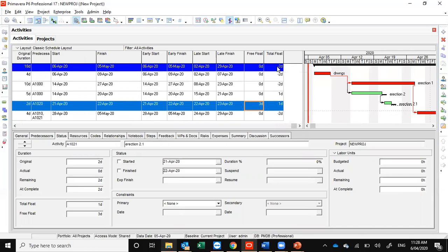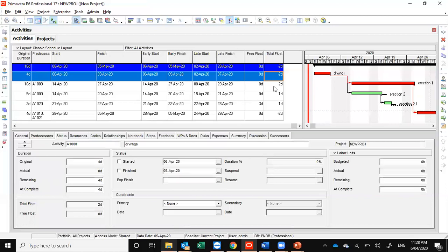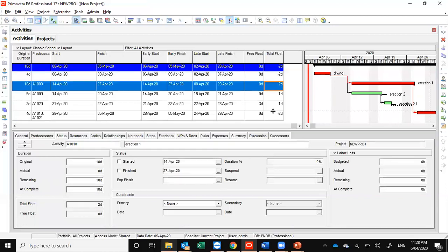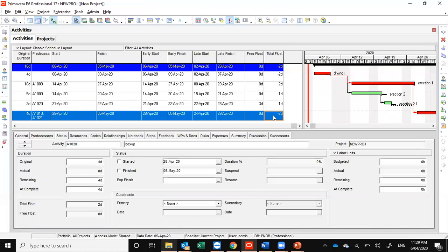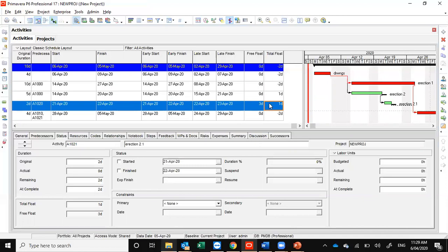This means the team has to complete the entire project before the finish date, or say 2 days before it. So it looks like some activity has to compromise its duration by 2 days. Mostly we have seen that whenever people get idle time in their activity, they will work on this extra load, or you can say the compression of activity. Once you apply must finish by, it will directly generate a negative float.